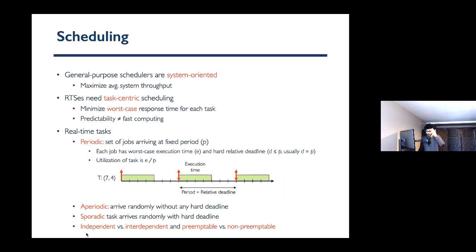They just come at some point. But that's not common. Usually there is one aperiodic task, which comes and goes, and that's it. And then the next one that comes is another task, right? So you don't put them all in one group. Whereas here, each one of these arrivals, we call them jobs, and the entire set becomes a task.